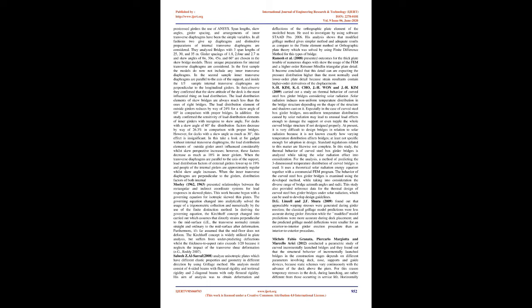In their study they showed that the skew angle of the deck is the most influential factor on load distribution. The load distribution factors of skew bridges are always less than those of right bridges. The load distribution factor of exterior girders reduces by 24% for a skew angle of 60 degrees in comparison with right bridges. In addition, the study showed the sensitivity of load distribution factors of interior girders with skew angle. For decks with a skew angle of 60 degrees the distribution factors decrease by 26.3% in comparison with right bridges. However, for decks with a skew angle up to 30 degrees, this effect is insignificant.